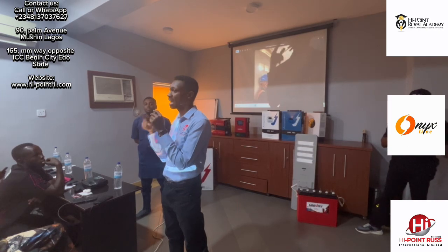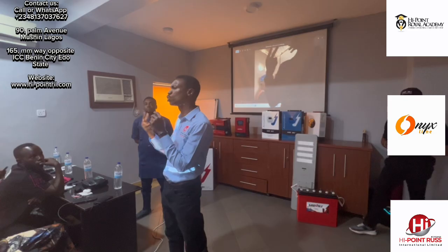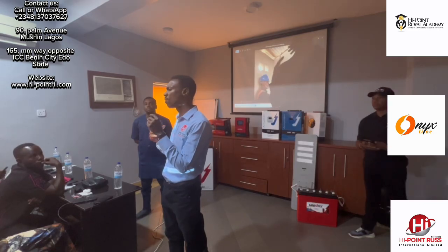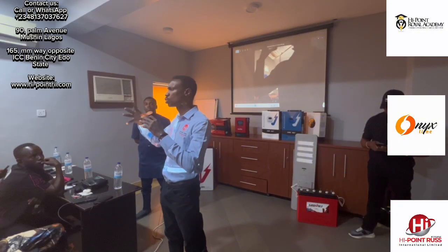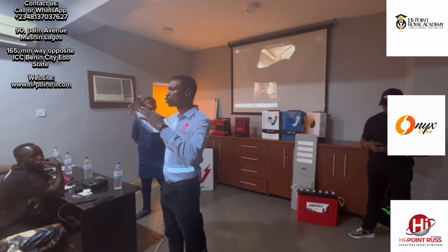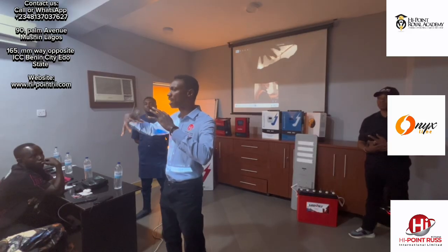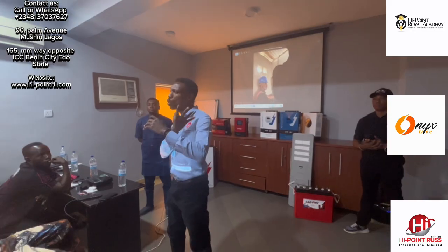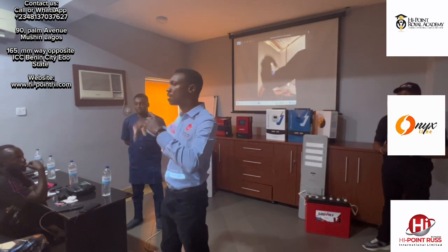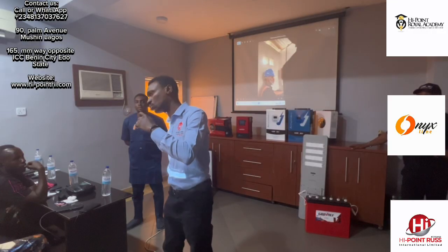Although what I've noticed from experience too is that if the PV voltage is very high, putting your battery into your charge controller first is a form of stabilizing. It first gives the charge controller the voltage range it should work with. Then by the time you introduce PV, it will know how to collect that.